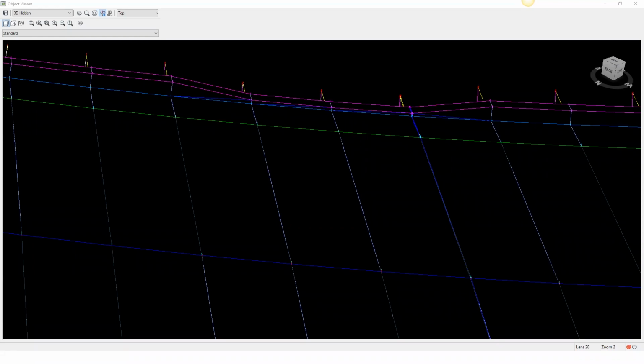I did get a question, just a thought: instead of using profiles, could you use offset alignments? That way you could more easily see where the curb transitions will be. Yes, I could come in and create an offset alignment and then create a profile off of that to drop it down. Makes it a little bit easier in that I'm not doing two profile views, but it would still be something that targeting that profile line, setting it to 0.5 down to 0.1 is the key on there.